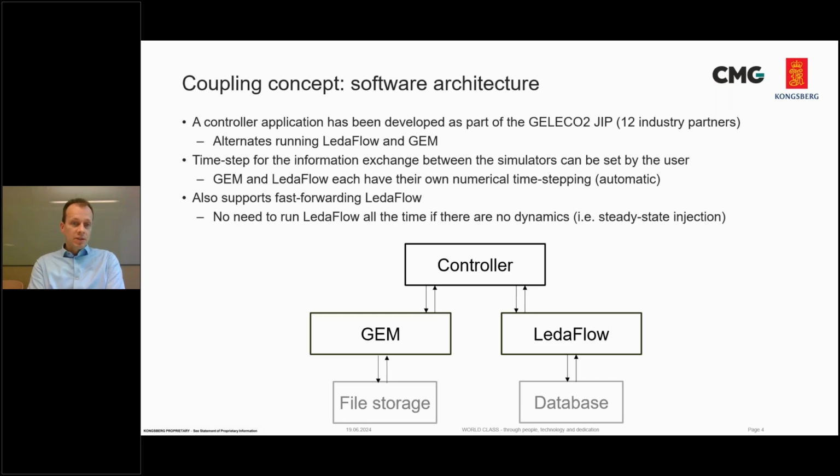The controller also supports fast forwarding LedaFlow in case you're running a very long simulation in GEM, maybe for a time horizon of several years. Then it's possible, for periods of time, to turn off LedaFlow, so you don't have to simulate all the time. And this leads to quite a saving in calculation time.